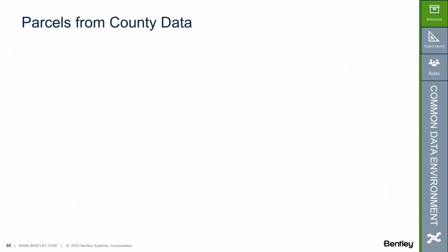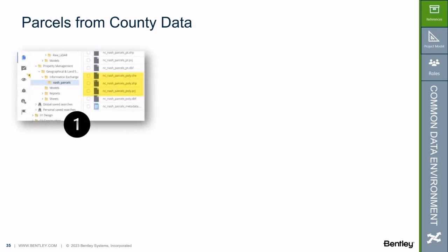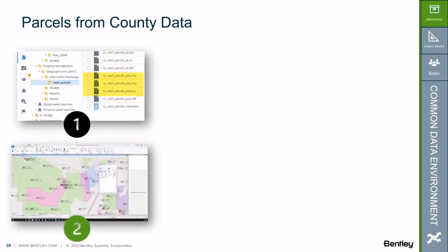As far as the parcels are concerned, what I did was I brought in the parcels from county data into the common data environment using four products and services. I used ProjectWise Design Integration, OpenCities Map, Design Review, and OpenCities Planner. First, the county parcels, I downloaded them and then placed them into the right-of-way and survey work area just as shape files. Next, I labeled the parcels in OpenCities Map. So I did a little bit of labeling there.